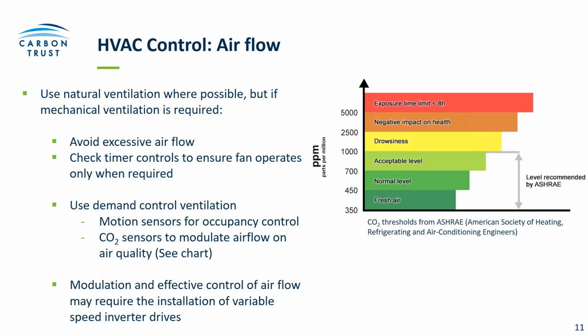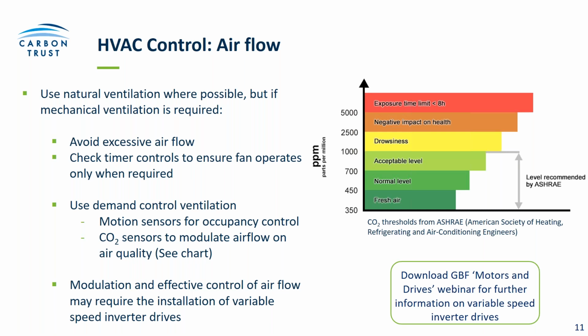And that need to modulate leads on to a need for variable speed drives. So you want to be able to vary your fan speed, and that's something we'll come on to later in the presentation. And there is more in our Motors and Drives webinar on variable speed drives and the use of inverter drives to control fans.